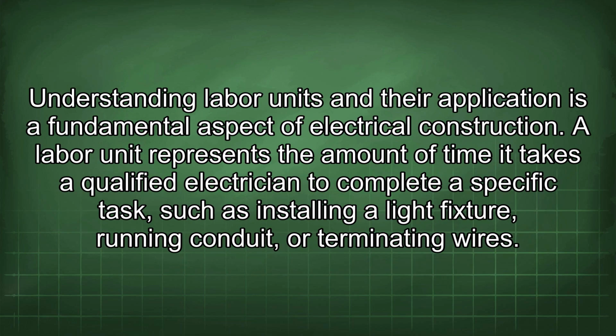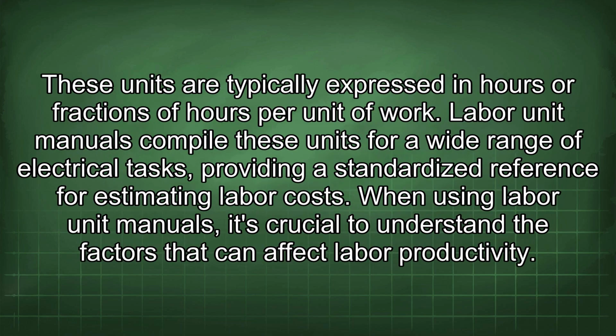Understanding labor units and their application is a fundamental aspect of electrical construction. A labor unit represents the amount of time it takes a qualified electrician to complete a specific task, such as installing a light fixture, running conduit, or terminating wires. These units are typically expressed in hours or fractions of hours per unit of work. Labor unit manuals compile these units for a wide range of electrical tasks, providing a standardized reference for estimating labor costs.